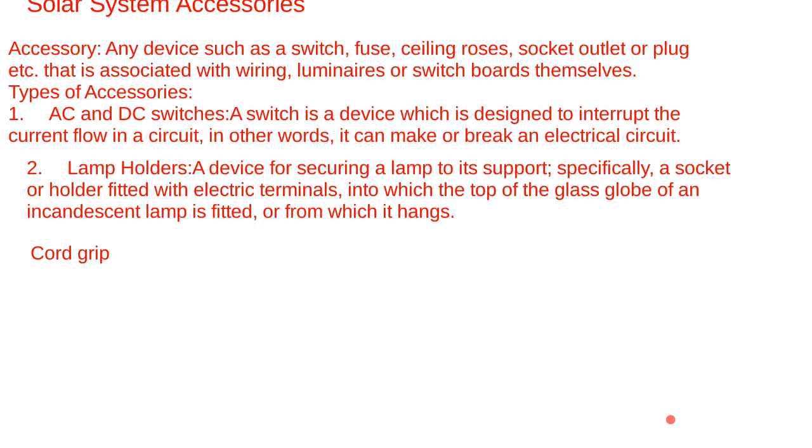The first one is the cord grip. So for this one, it's where the lamp holder includes a cord grip. It is gripping the lamp being the bulb, to secure that cord, and it is suspended as a pendant light. The common types include the compression fitting, the looping the cable around the internal obstacle, or a screw which presses the cable. So that is the cord grip.